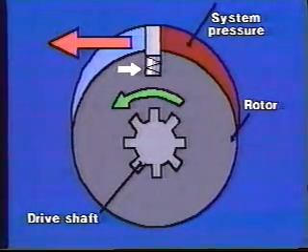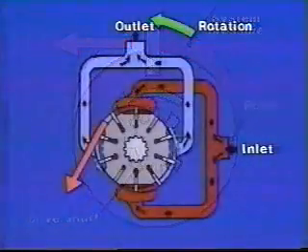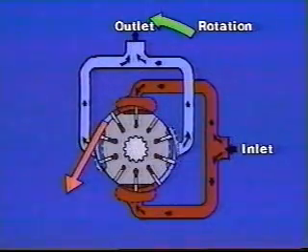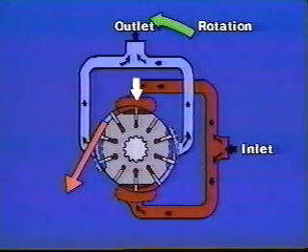If this vane weren't held out by some force to begin with, oil entering would just scoot from one side to the other, and no torque or rotation would develop. Here we have a balanced vane motor, very similar in construction to a balanced vane pump. Hydraulic loads developed on this side are canceled out by hydraulic loads developed on this side.